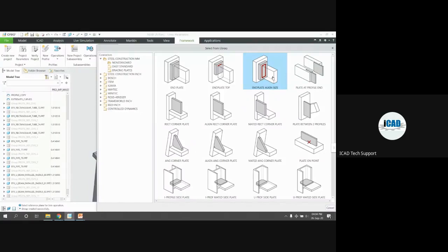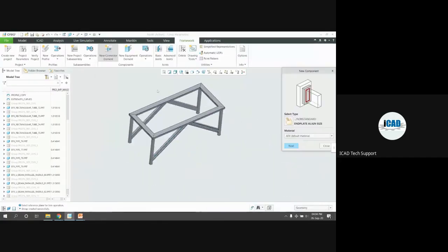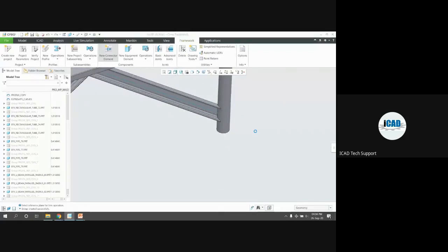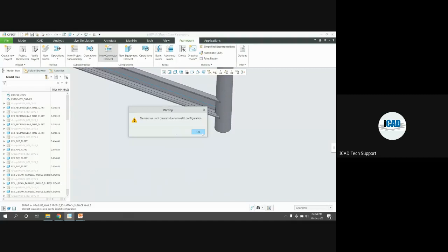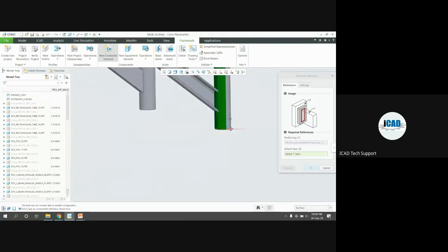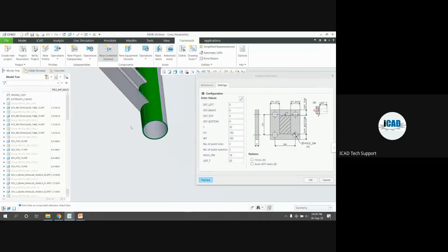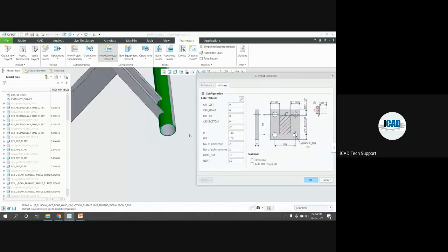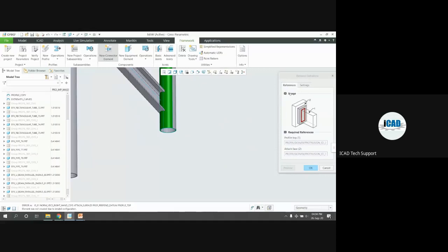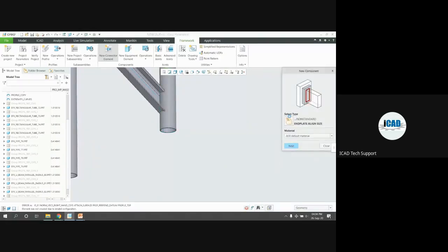End plate align sides, I want to use. Click on this. Click on next. Just click on preview. Element was not inserted for that surface. Click on preview. So for the round ones, a rectangular reference will be created. So here I am using the end plates only.